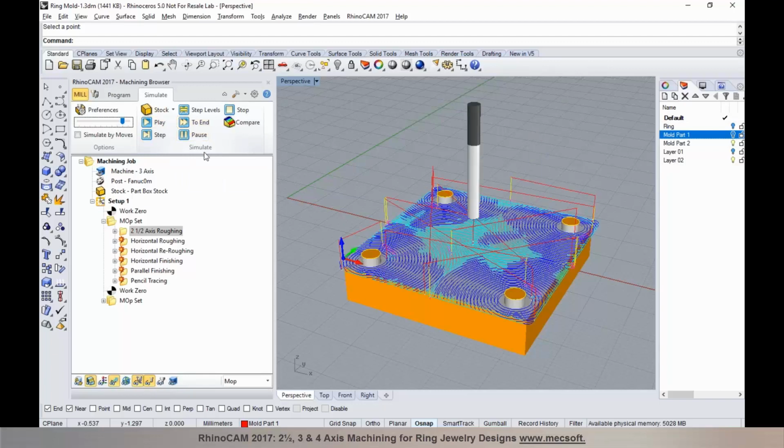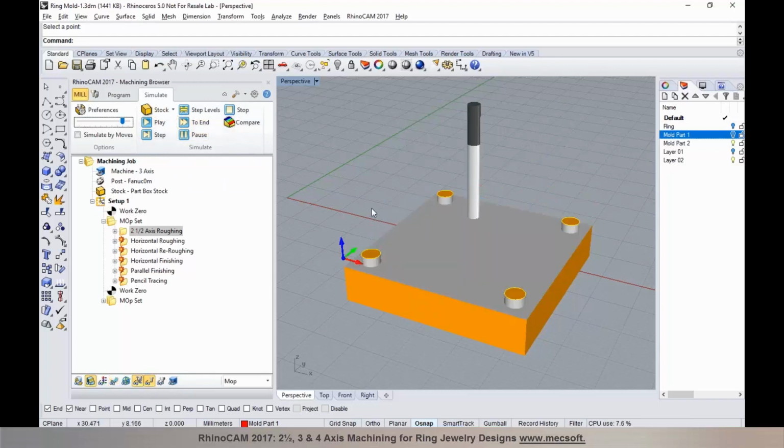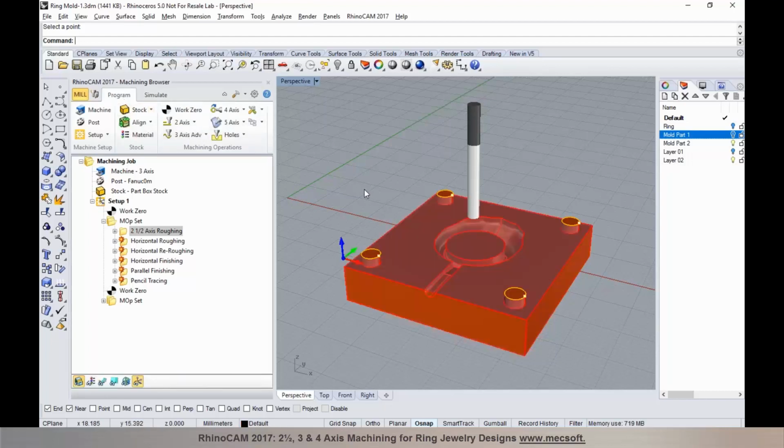So this is very similar to roughing in 3-axis. However, here, you're using a roughing for 2-axis operation for radial for prismatic parts. And as Joe pointed out, this automatically takes into account the extents of the stock that you defined. In this particular case, it just happens to be a rectangular stock, but if you're using a stock with any other shape, cylindrical or any odd shape, it'll automatically take that into account.